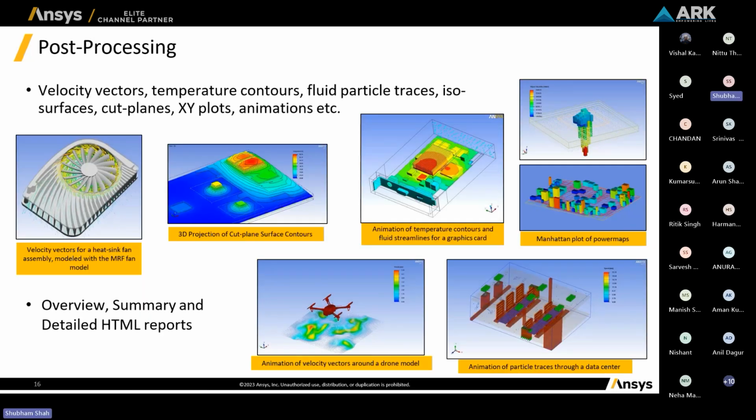Now coming to the third part, that is post processing. What do you understand by post processing? Let's say we have performed the simulation, but how do we analyze whether our component is getting heated up, where it is getting heated up, what the location is, and what the temperature is? For that, we can look at the cut plane.